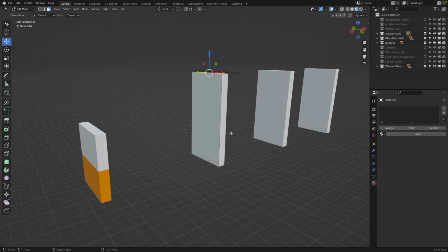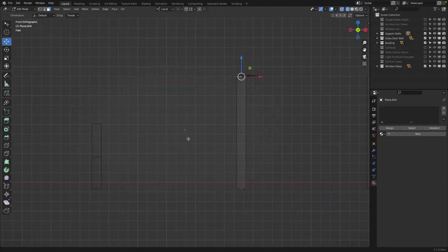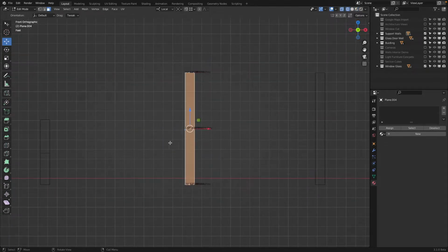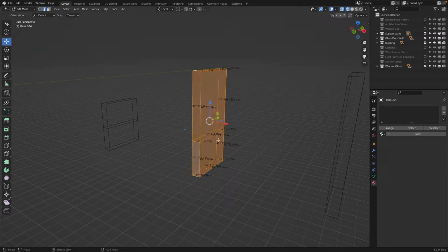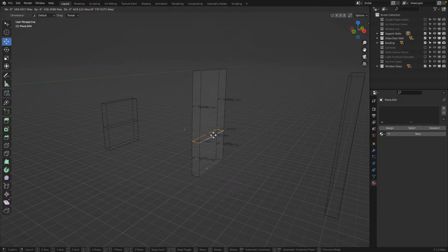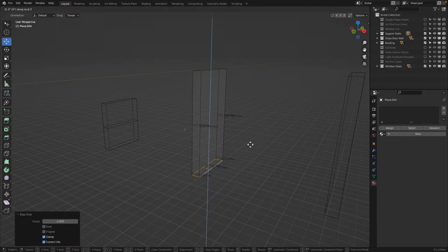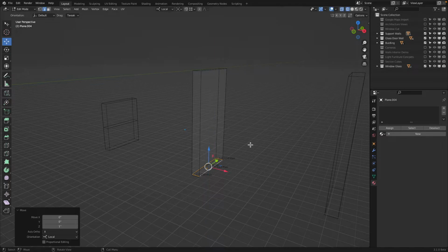So let's go to here. Let's do the same. Let's assume the Control R for loop cut doesn't work. In edit mode, I can press K for knife. Then this is the x-axis, and then cut through, C, click, enter. There's my loop cut. Also here, alt click on this edge, GG, GZ, what was it? 1 meter, not 1 inch, 1 meter.